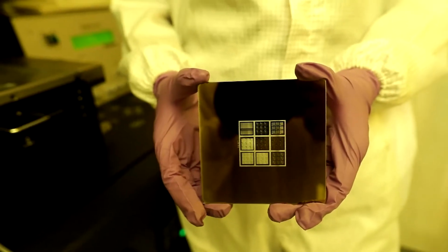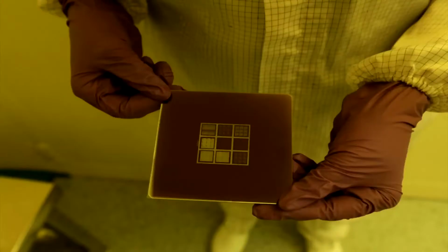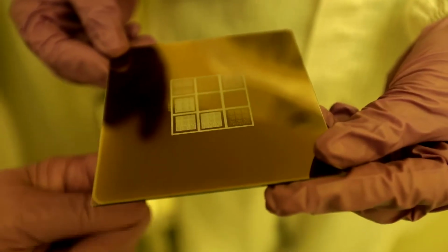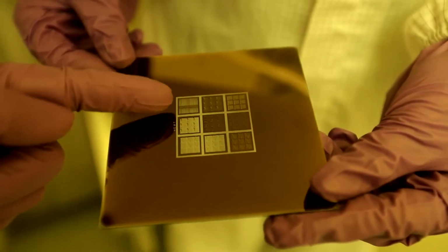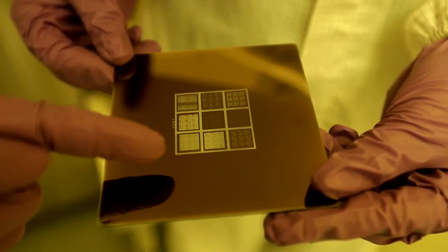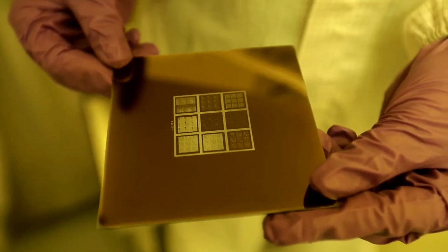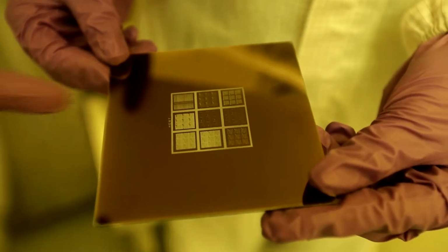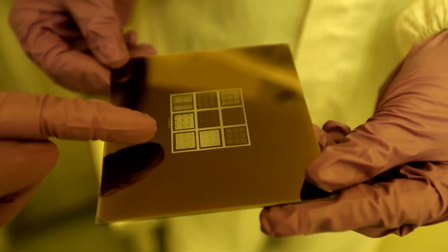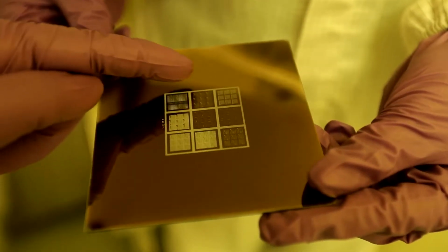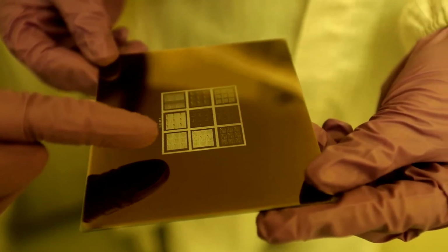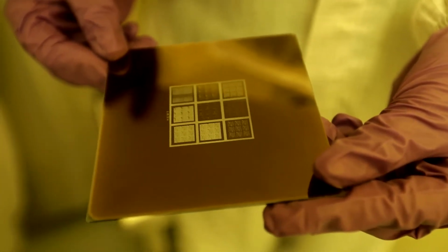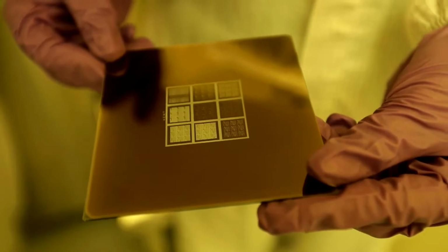Now, let us see the photomask. A photomask is an opaque glass plate with transparent features written on it. Photomasks are made by a fabrication process where a computer-aided design is transferred to a thin layer of chromium on a glass or fused silica substrate. So now we are going to transfer these patterns, shown on the mask plate, onto this silicon dioxide substrate.